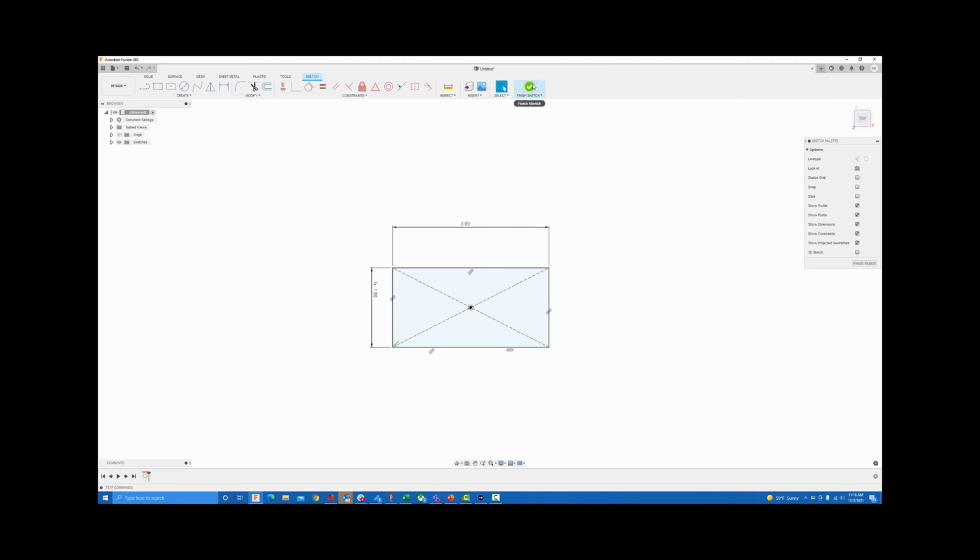With this, I'm going to finish this sketch. In fact, before I do that, this is going to be kind of rough. I'm not going to worry too much about dimensions, but this example is something I used to design a bike light. I'm just going to put 2 circles. I put an equal constraint so they're the same size, and we'll just do something like 1 inch there. I'm going to dimension to the center of my box and the center of my circle, and we'll do 0.75, and the same thing here.